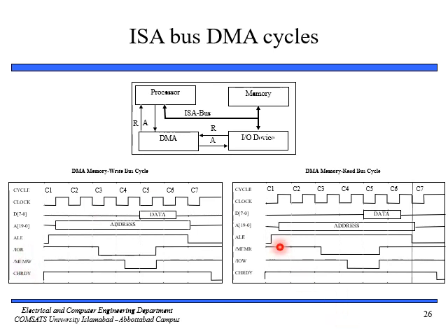So the rest of the things are the same, that we are reading the data in the 5th or 6th clock cycle. We are holding the address throughout all the clock cycles. For this we are using address latch enable. So to keep the address on the bus we are using a latch. So this is memory read.